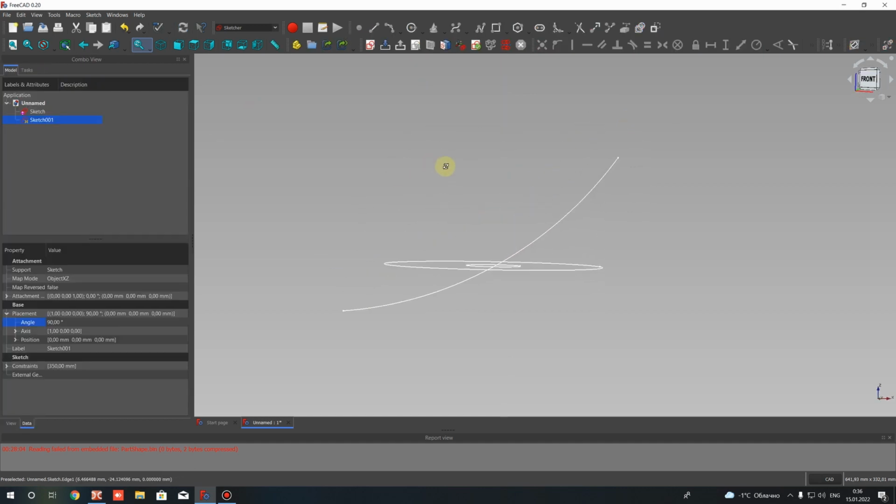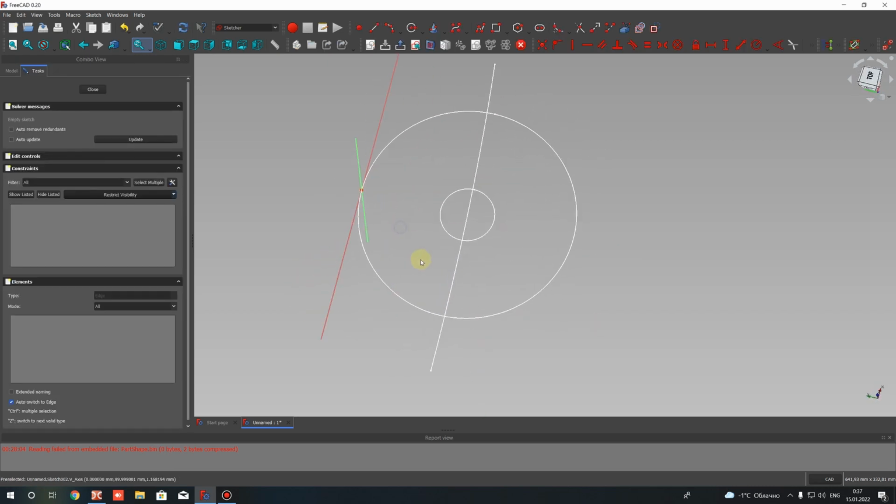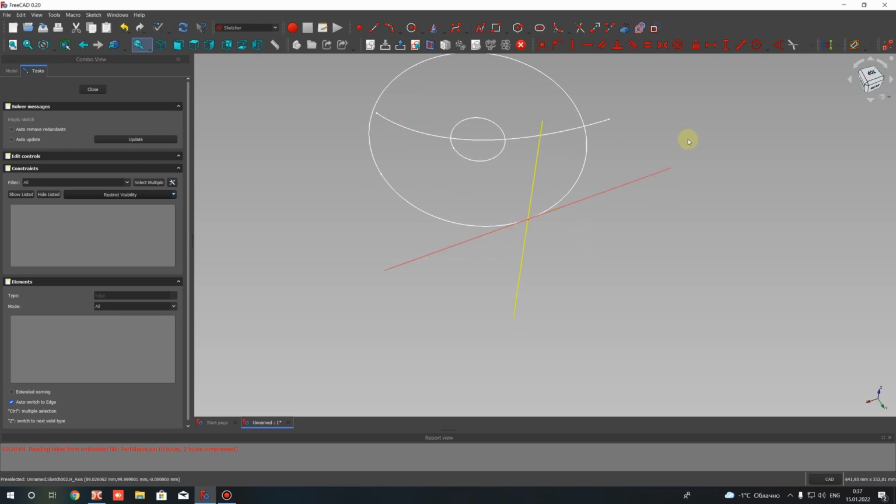You will get this shape here, and let's create one more sketch in the XZ plane, and let's go to the external part of our sketch. We will get here the shape, the external part of our propeller. Go to rear and let's create another circle here.